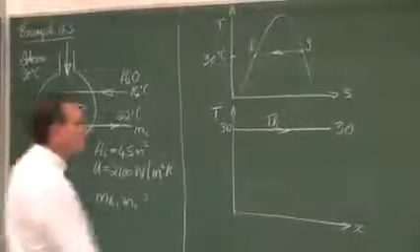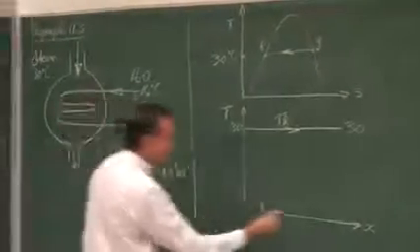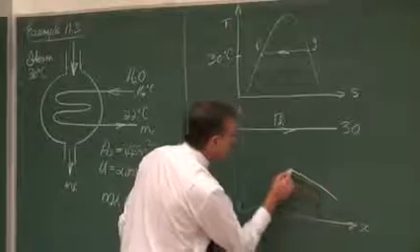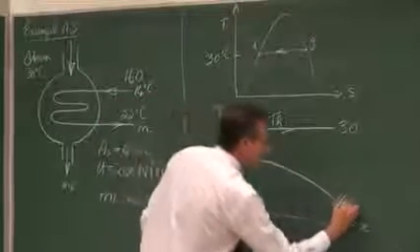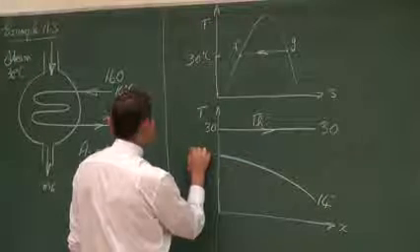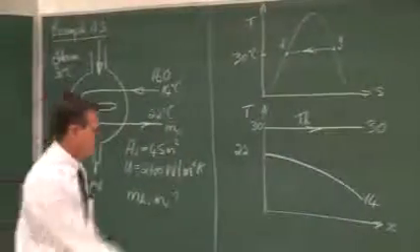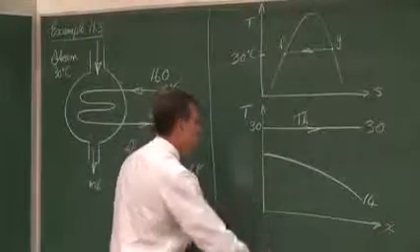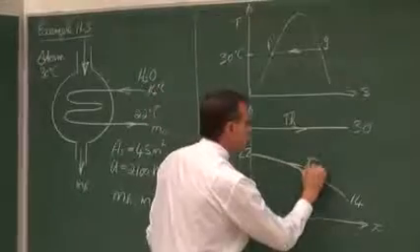Now, to condense that steam, we've got cool water from a lake which enters this condenser. So it enters at 14 degrees Celsius and it exits at 22 degrees Celsius. And that is the cooling side.